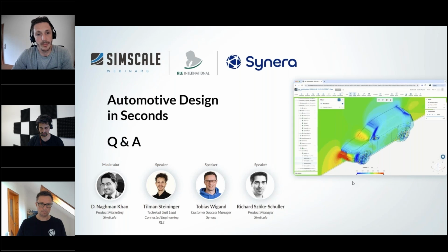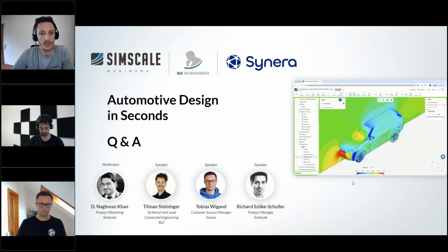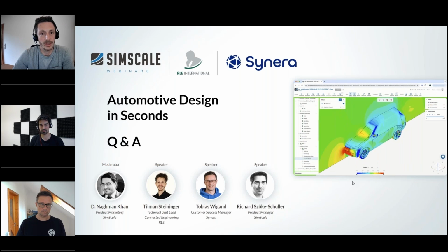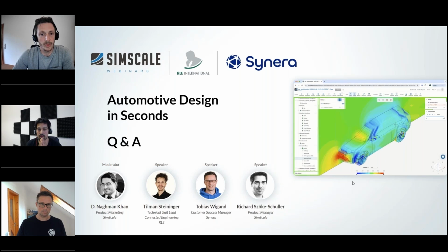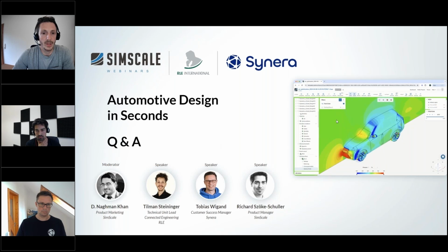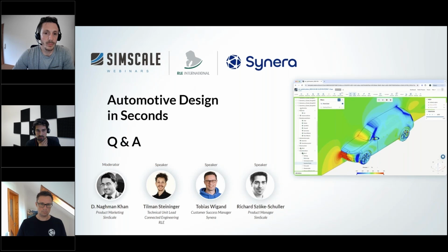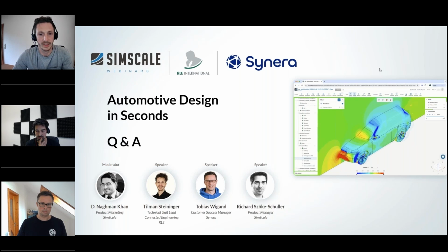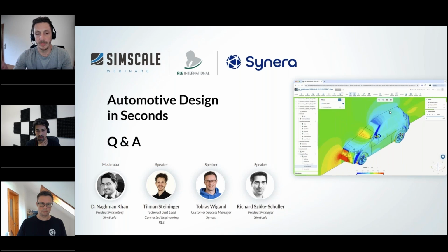But we were also looking a little closer into head impact situations on an interior instrument panel, which is again something CAE related in the development process, where it is important to see which parameter sets, in terms of rib height, rib wall thicknesses, overall material behavior, and so on, perform best for absorbing energy. So there's a lot going on.